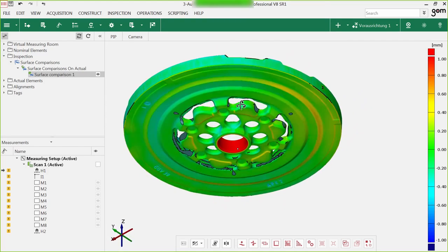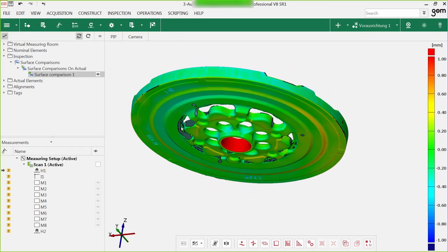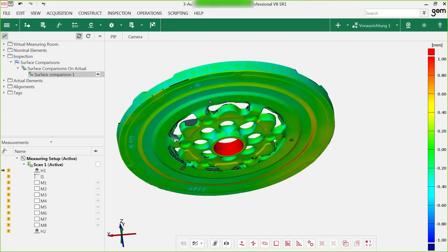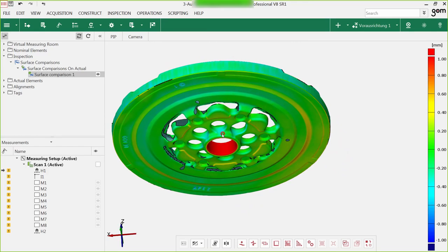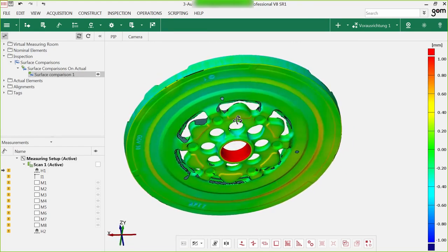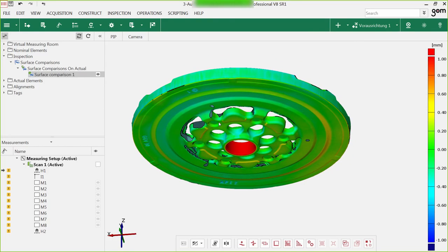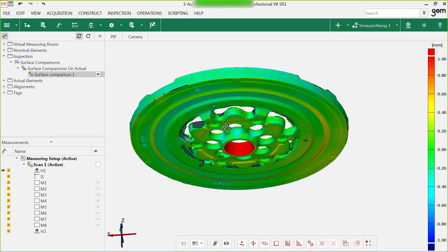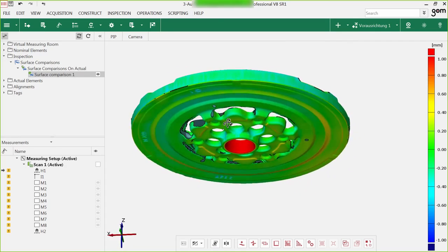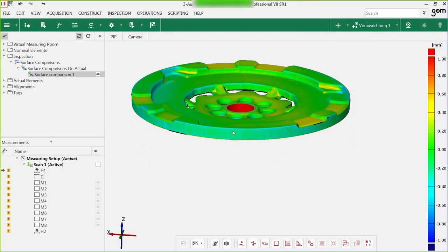You see the nice coverage, but on the downside, on the bottom side, you'll see still a few patches, a few gaps that the software didn't capture. But that is not a big problem. You can just insert a few inspection elements before running the function, and that will get you a nice coverage of the whole flywheel.